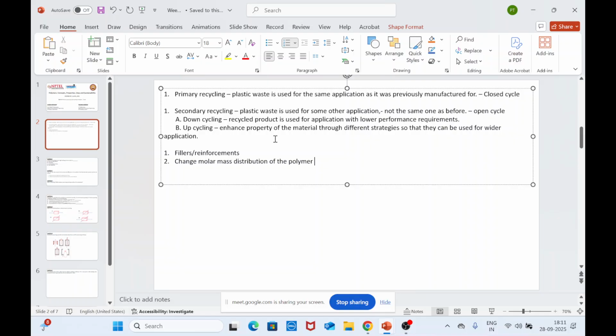So this is about recycling again. Before you do this recycling, you have to do pre-recycling operations as well. These are common to all the recycling operations. First you need to do separation and sorting, to make the recycling process efficient. Then you do volume reduction, so that the mass or volume of the material is not so huge that it becomes difficult to recycle.